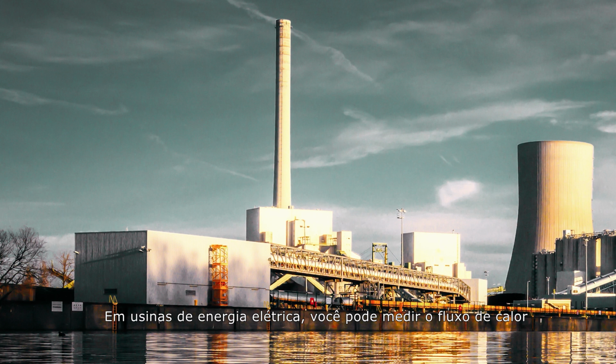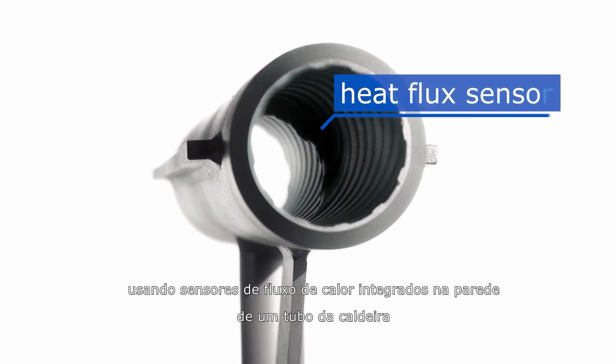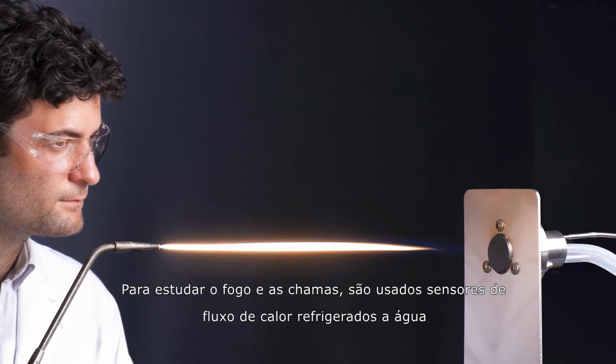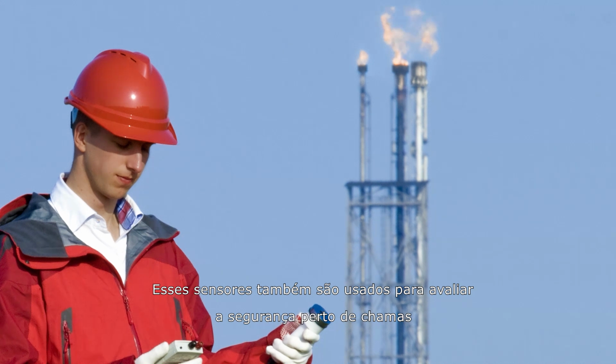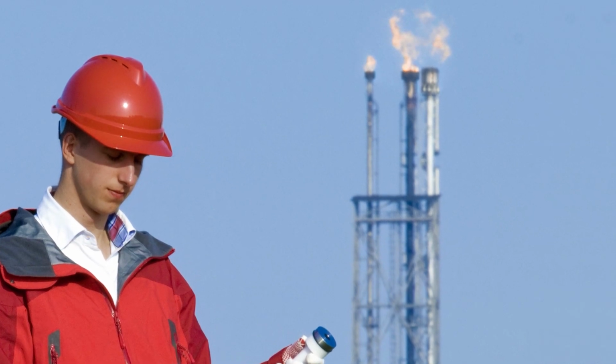In electrical power plants, you can measure the heat flux from the boiler wall to the steam, using heat flux sensors integrated into the wall of a boiler tube. To study fire and flames, water-cooled heat flux sensors are used. They have a black front surface that absorbs the radiation. Such sensors are also used to assess safety near flares.